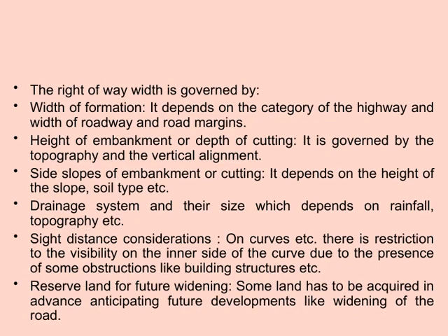The right-of-way width is influenced by several important factors that we need to consider carefully. First, the width of formation, which depends on the category of the highway, as well as the width of the roadway and the road margins. Essentially, wider roads or those designed for heavier traffic will require a broader right-of-way.